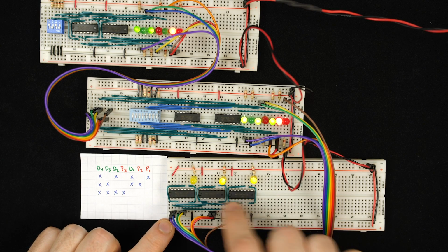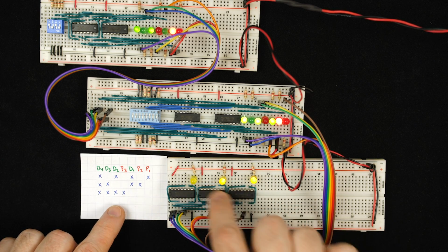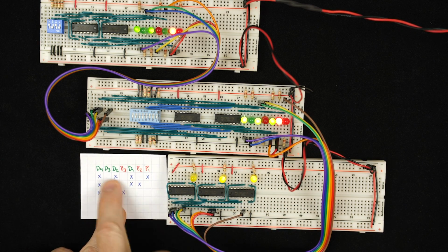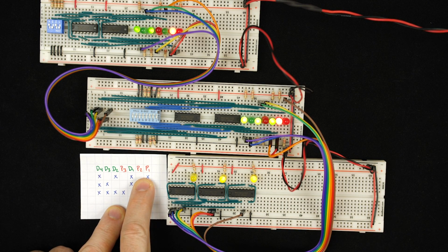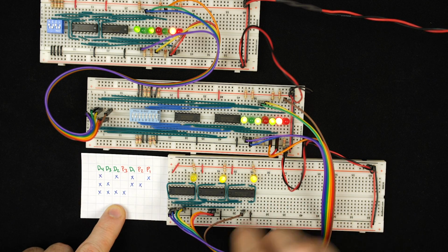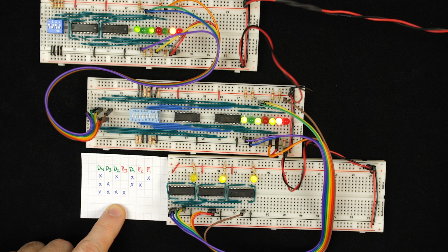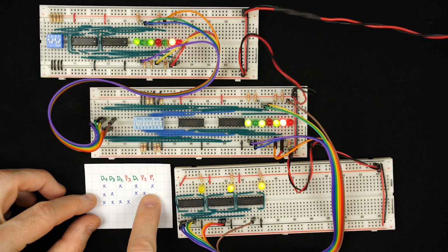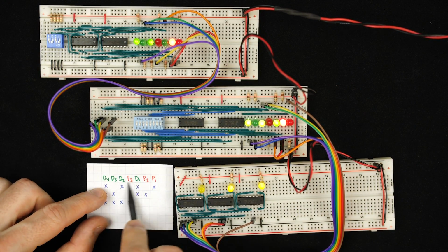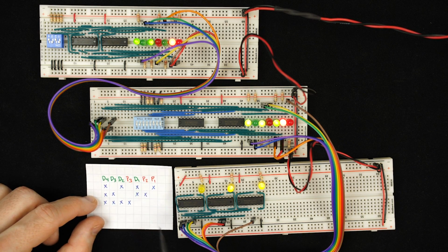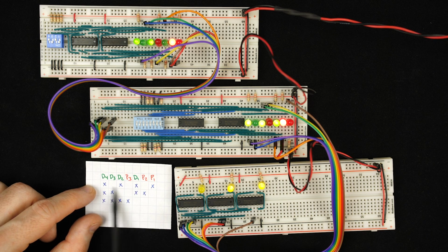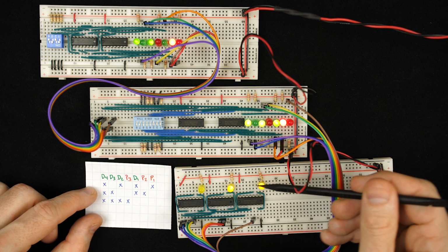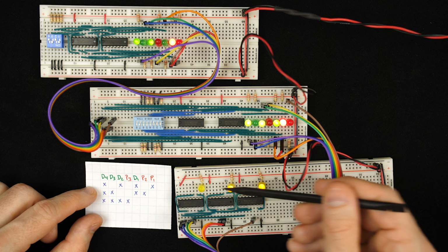We're able to detect it, and from which parity bits are set, we're able to figure out which bit was flipped. And so presumably we can build further circuitry here to actually flip it back the right way. But before I get to that, one thing that you might have noticed is the way this is laid out. Perhaps you've wondered why I interleaved parity 3 in the middle here, why it's grouped like this. Well, it's grouped like this because the actual parity bits here read out exactly which bit is wrong.